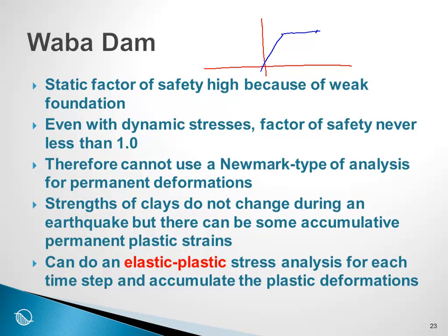But during the earthquake analysis, we might get some reversal and we get some plastic deformation and then some more plastic deformation. Eventually, at the end of the shaking, there will be some accumulation of the plastic strain during the shaking. And that is what is being done here by taking the quake results into SIGMA for an elastic plastic deformation at each one of the time steps for which data is being stored.